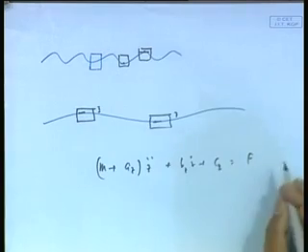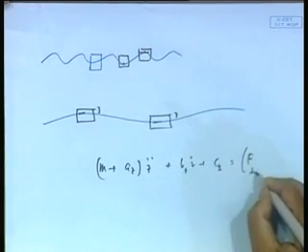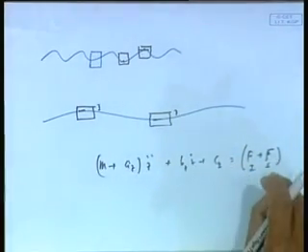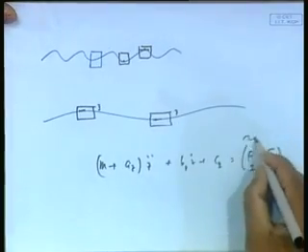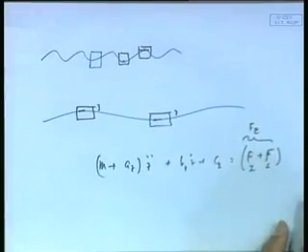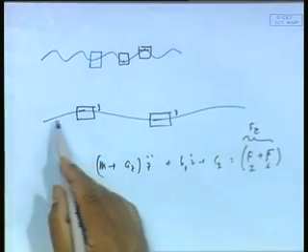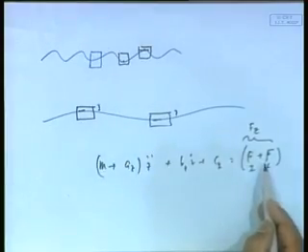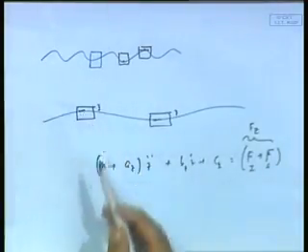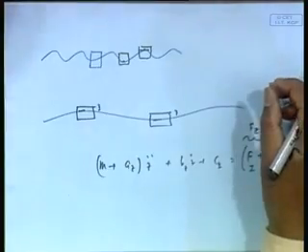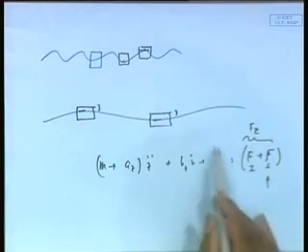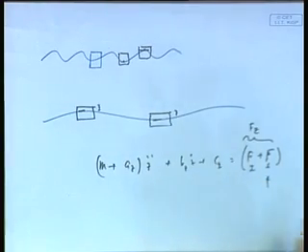Again, if I were to look at this equation of motion, in fact, even this part has got two parts. Actually, as I said in the first class, the incident wave and the scattered wave together combine and give this Fe, in principle. Now, at very low frequency, the body is going to disturb the waves very little. So, scattering also is very small, because with a very long wave, the body simply goes up and down. Since it goes up and down, it is not diffracting, and it is not going to disturb the wave field. Even if the body was not there, the wave looks exactly the same. So this becomes very small as such, because this is also proportional to omega e. So you end up getting only this part, very easy to figure out, no problem at all.